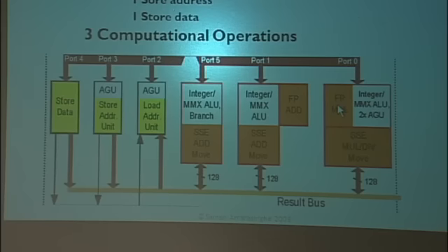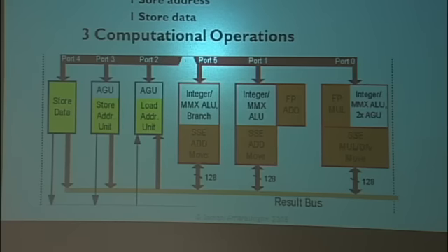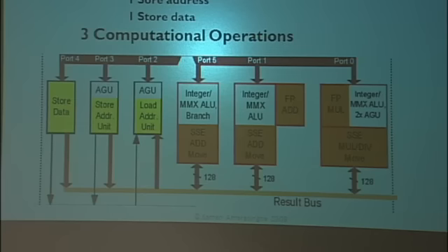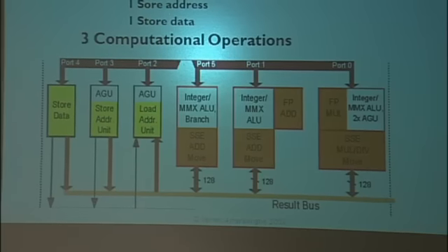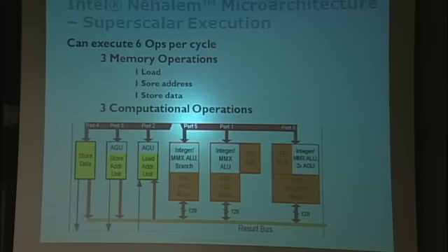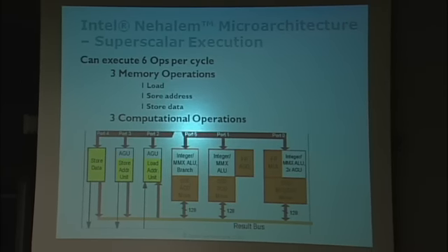So this complex hardware will figure out, okay, if you have these instructions, which of these execution units are available. If the instruction is able to execute, it will put it into one of these and get the results out. So if you are lucky, you might get about 6 instructions going each cycle. If you look at the measure we call clocks per instruction, it will be 1/6 if you are lucky. If you can run the machine to the metal, that means everything is working all the time. It's very hard to find that kind of program, but we'll see whether you guys can get something like that. That would be really cool.